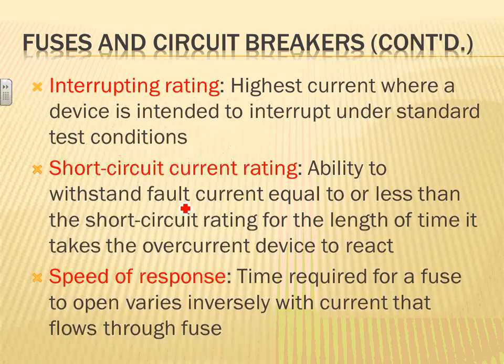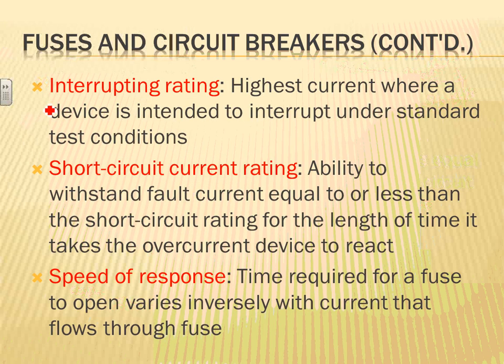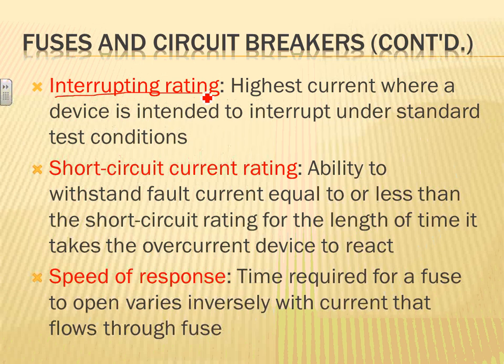Okay, so that one. The other thing is, when it comes to circuit breakers, there's three very important values. The most important one is, of course, the full load amp, the continuous load rating, or the 80% of the continuous load. That's the full load amp rating of that circuit breaker. The second one is the interrupting rating. This is the highest current that the circuit breaker can interrupt with minimum damage to the equipment, based on the rating. So that's how much current the circuit breaker can physically, mechanically interrupt, heat and magnetic wise.